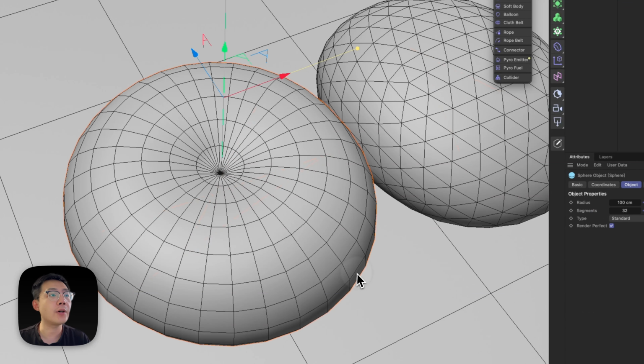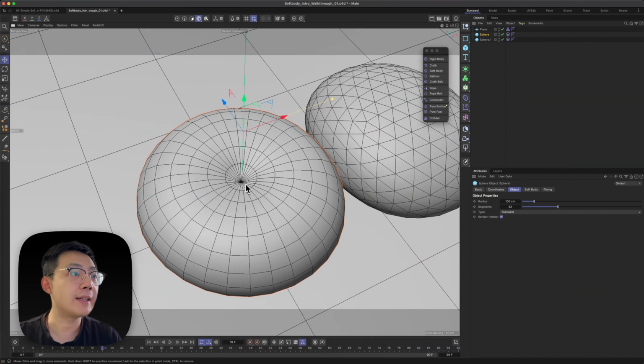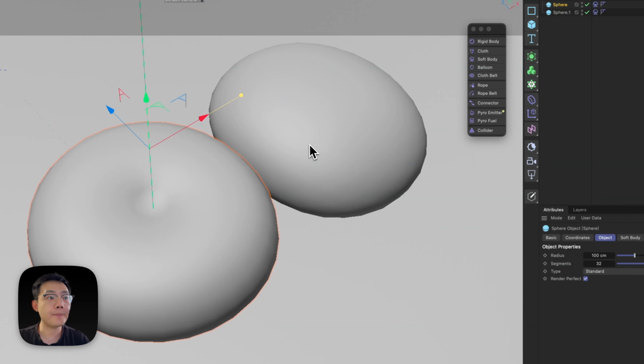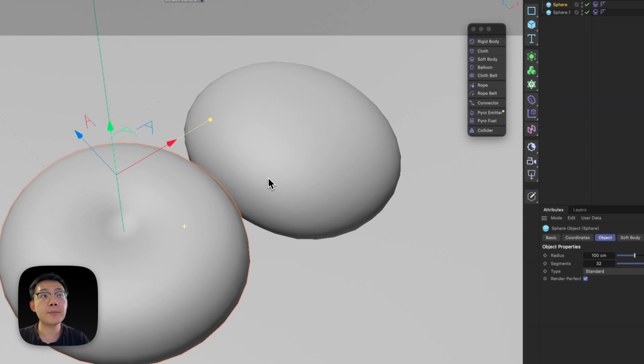These are kind of okay geometry. They are stretched out evenly, but this is very dense. So whenever you have a dense topology, you will be facing some of the issues like this dimple. All right, so I just want you to remember that, and we can keep going.